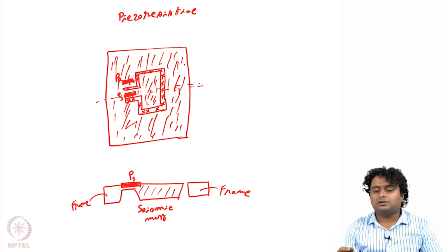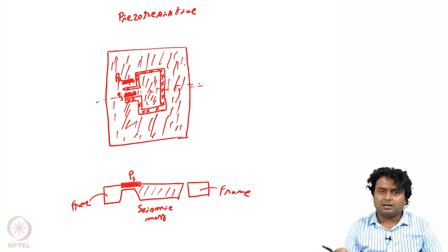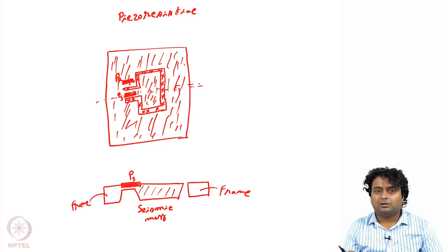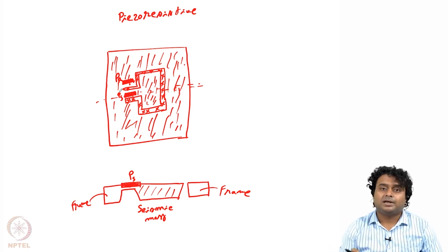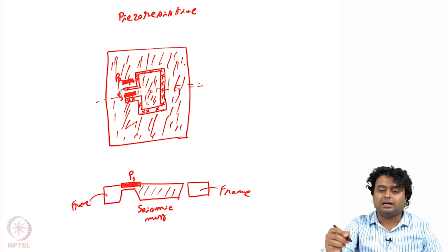The advantage of having this kind of reference resistor is, let us say there is some change because of the temperature or applied voltage or any other parameter which is common to both cases, the reference resistor as well as the sensing resistor. Those effects will get cancelled out, because if the resistance is changing because of temperature, then it will change similarly for both of them.